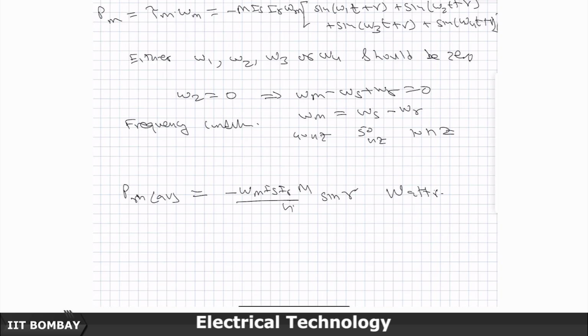So, this is your single phase machine. One example of the single phase machine is the fan. Now, the thing is you cannot just start with single phase. You need to create a rotating magnetic field, for which at least you need two phases. We will discuss rotating magnetic fields again in more detail later on, but by itself these are not self starting machines. So, if you open up the fan and see, actually you will see the single phase motor as we discussed here, but another winding is required, connected across a capacitor.